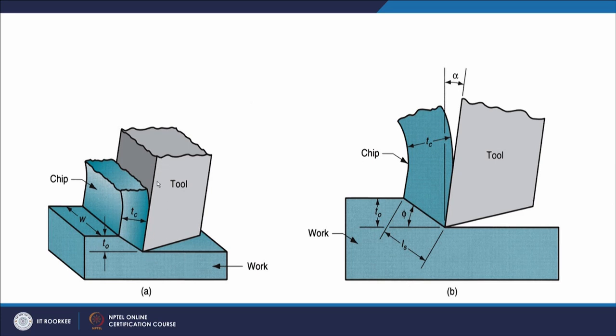we see this is the cutting edge. The cutting edge is running all along this width, and this is the clearance, there will be the rake, and this is the plane along which shearing will be taking place. This is the uncut chip thickness, and this is the width of the cutting edge as well as the width along which the material will be removed during the machining.